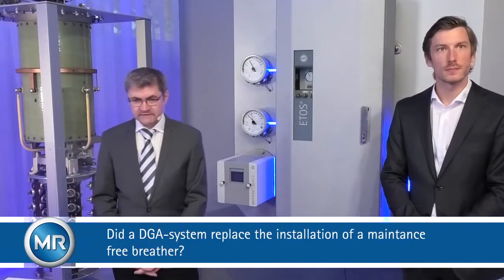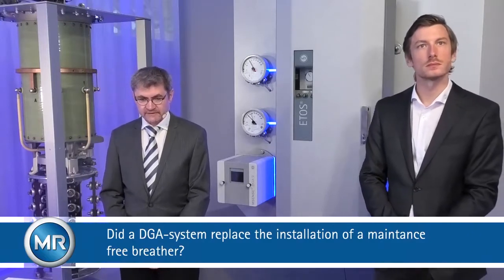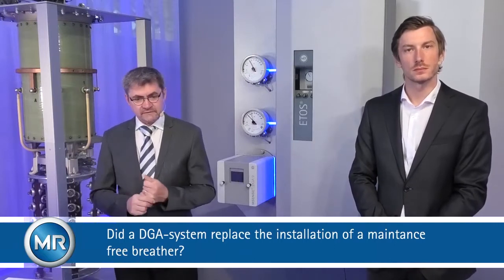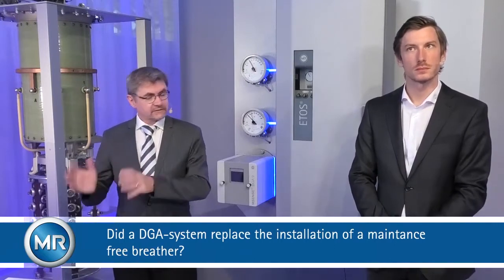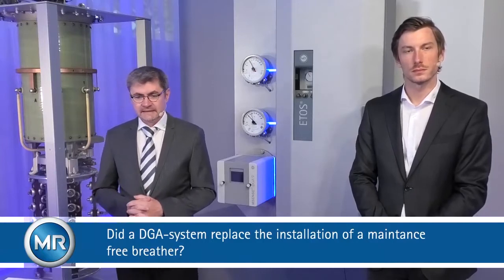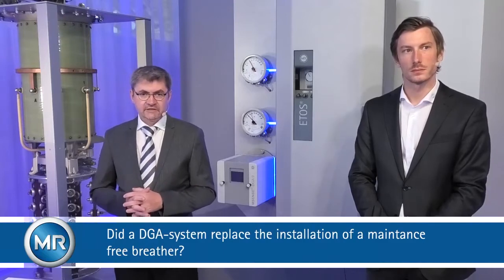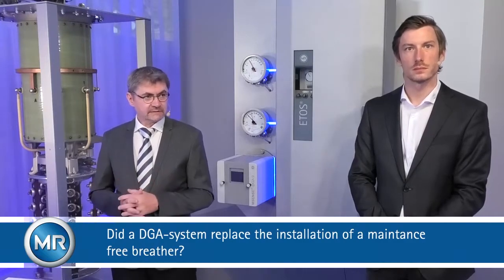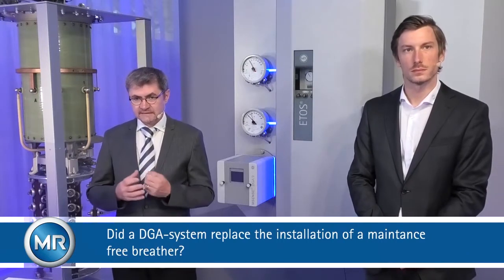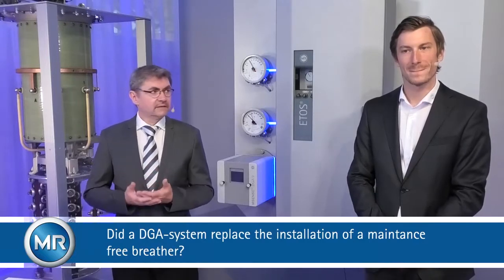The installation of a DGA system does not replace the installation of a breather. The function of a breather is to get rid of the moisture from the outside, so that it doesn't get into the oil of the transformer. It's more or less an active part. It's a demoisturing system. The DGA is an analysis system. You get information about the concentration of the gases and the concentration of the water content in the oil.